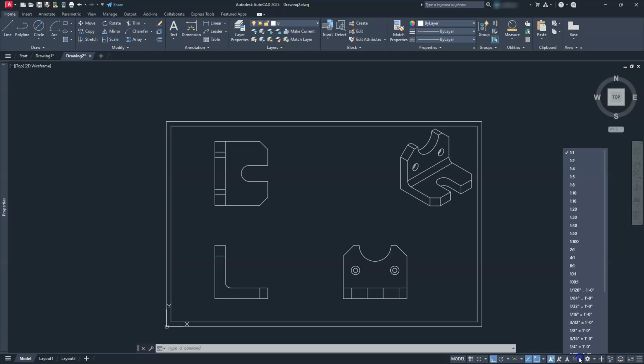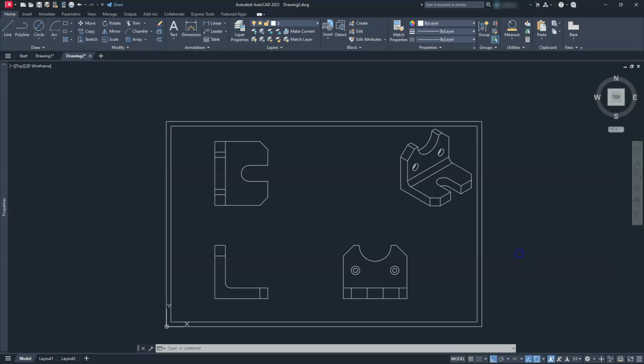So I'm going to be doing everything standard. If you're going to do the standard option, the first thing you need to do here is set your line type scale. So LTS, enter. Set this number equal to whatever your scale factor is. And in this case, it's going to be 35.